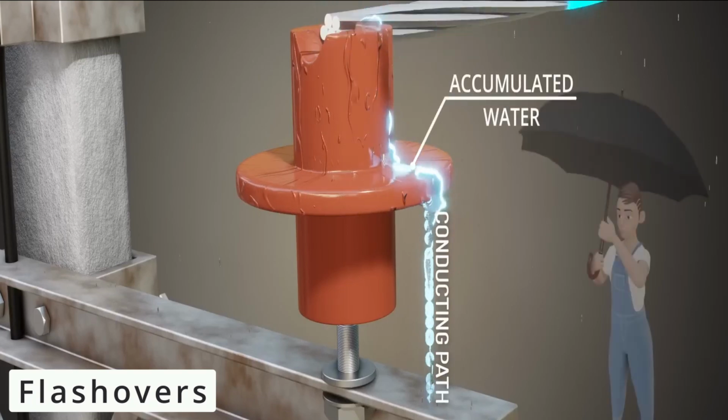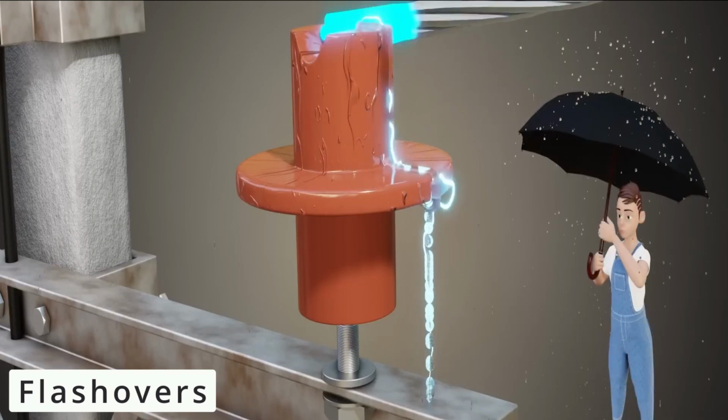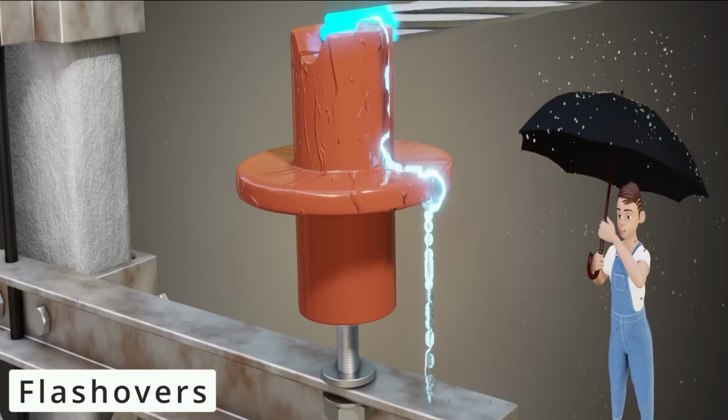This occurs due to many things like a failure in one plate of the insulator string, or there is contamination on the insulation string which shortens the distance to the tower and flashover occurs.